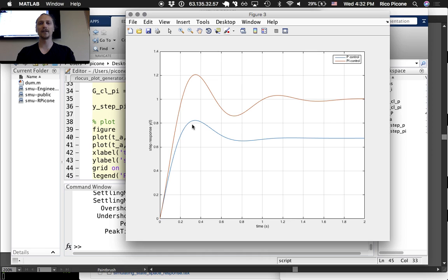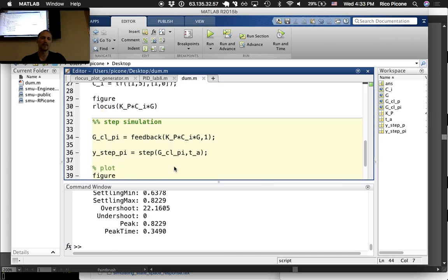And so yeah, P is, the transient's a little bit better for our P control. PI control, the steady state's way better, but we lost a little bit in our transient. So we could do some things. We could start to increase the gain to see if that helps get us back under with our transient, with our settling times. Our settling time is probably more like 1.5 now instead of 1 second. So we sort of lost that spec a little bit. If we looked at it,